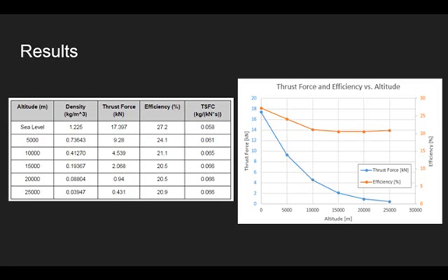This system design could be modified to have different parameters, such as a more optimized area relationship throughout the ramjet. The analysis performed was based off set Mach numbers, with the exit at Mach 3, and researched geometry to ensure valid results. The system also employed an ideal case analysis with minimal to no heat loss during the operation. It had constant fuel delivery and constant specific heat. Further optimization could be performed on the throat and nozzle exit of the ramjet that would facilitate better results on the output system.